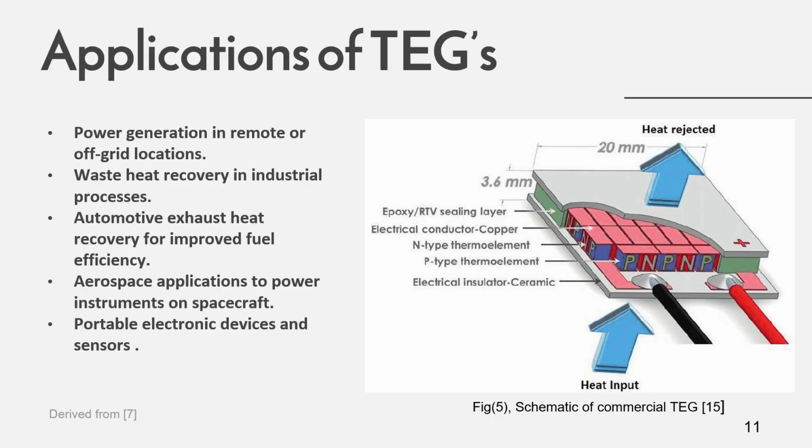So we have discussed some of the basics related to thermoelectric generators, and coming on to the applications, TEGs find application in power generation in remote off-grid locations, waste heat recovery in industrial processes, automotive exhaust heat recovery for improved fuel efficiency, aerospace applications to power instruments on spacecraft, and some portable electronic devices and sensors. And here we have a schematic of commercial TEGs, and we can see how the pillars are arranged electrically in series and thermally in parallel.